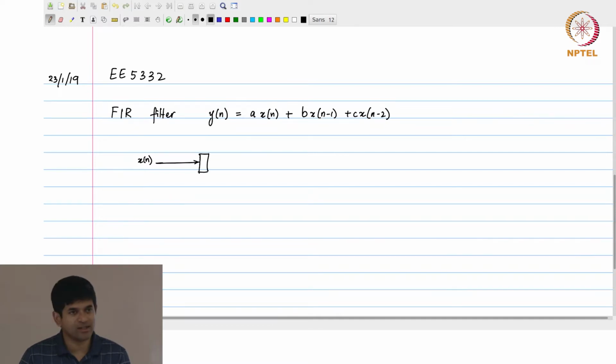The shift register essentially says there will be some block which I am going to just use a rectangle to represent, and at the output of that block is going to be x of n minus 1. The implicit assumption over here is that I have some kind of a signal which is basically the sample clock which is going to come to this register. I am not going to draw the clock from now onwards. I am just going to assume that whenever I draw a rectangle like this, it is understood to be a shift register. There is another shift register because I also need x of n minus 2. Of course it has the same clock, otherwise it would not really make sense to use a register like that. Alright, so far so good. I have got x of n coming in from somewhere, and from that I am deriving x of n minus 1 and x of n minus 2.